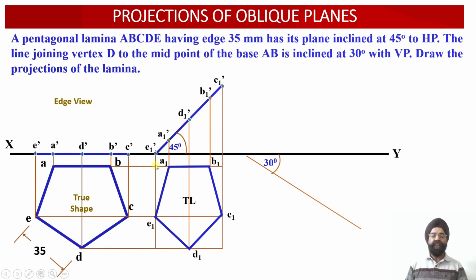Now once again, using the rectilinear distance method, we are going to transfer this pentagonal plan projection view into this position over here. Now how can that be done? We have this rectangle, please check, which we have drawn to inscribe this pentagonal apparent shape projection over here.